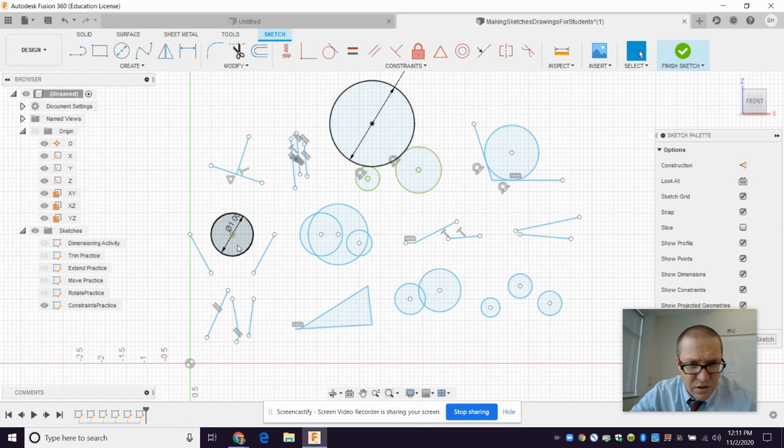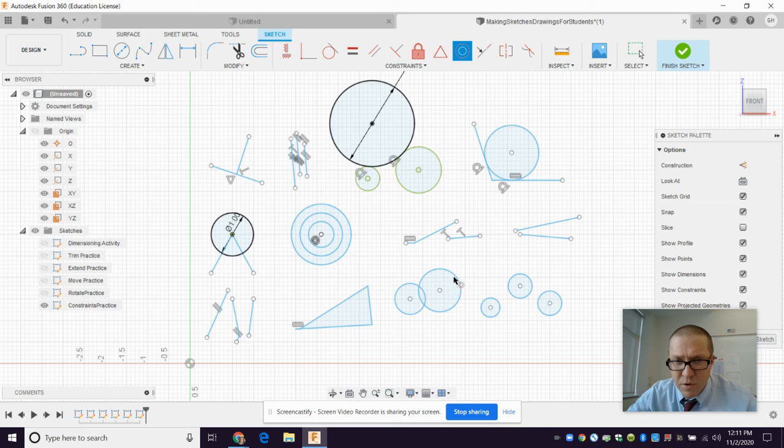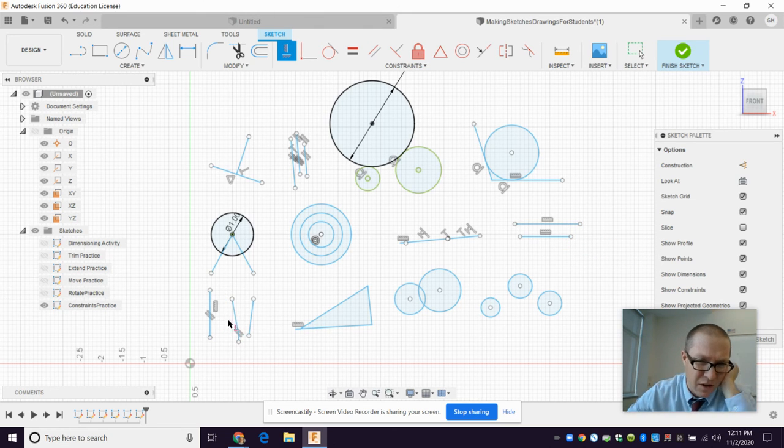All right, so this one sets the fixed point C, which I think looks like it's already fixed here. And then use the coincident constraint, which is that first option. Here to here, and here to here. That's good. This one's coincident. Boom, boom, boom, boom. Lines them all up. Collinear, this option. Boom, boom. These ones horizontal, vertical. It guesses for you. It's kind of cool. I guess it must think, whatever it's closest to, 90 degrees, it picks.